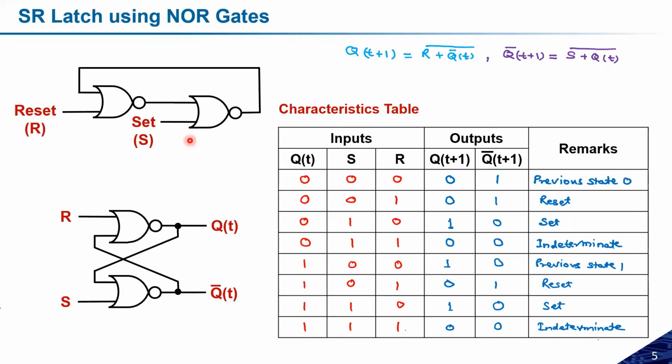In this case, one of the input and output pairs is utilized to connect input and output, and the second input is used for external triggering. The problem with the inverter, that we cannot externally trigger, can be removed with the help of a NOR gate or a NAND gate.